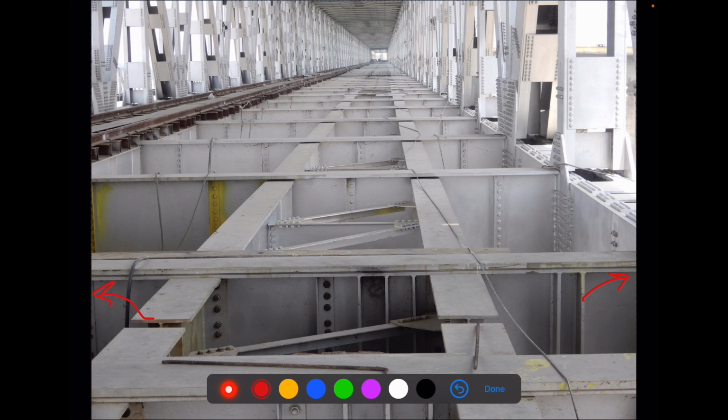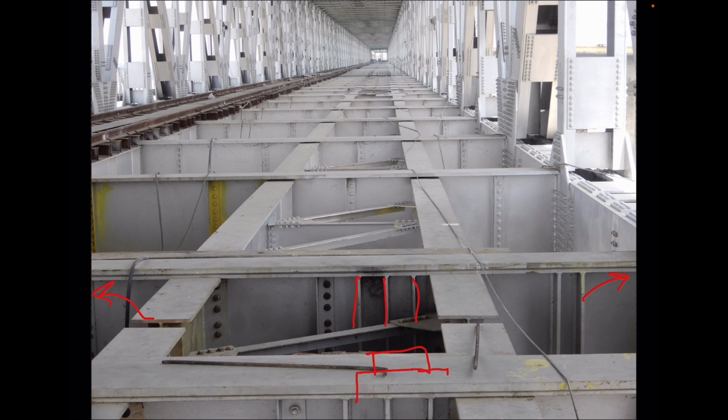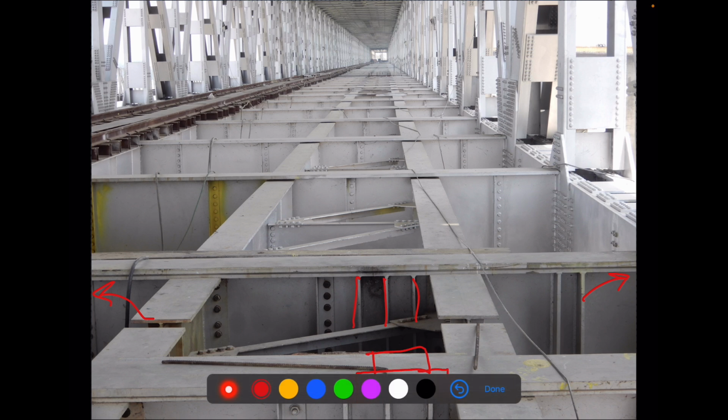So it looks like these stiffeners are jacking stiffeners, provided for putting a jack over here so that the web does not buckle. So this looks like the jacking arrangement. A similar arrangement was there near the second track. So there are two jacks. We have the facility of providing two jacks for lifting these girders. So this was it. What else is visible?